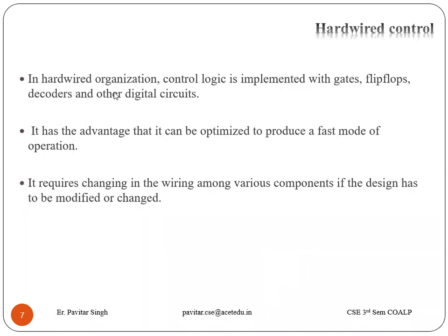In hardwired organization, control logic is implemented with gates, flip-flops, decoders, and other digital circuits. It has the advantage that it can be optimized to produce a fast mode of operation.